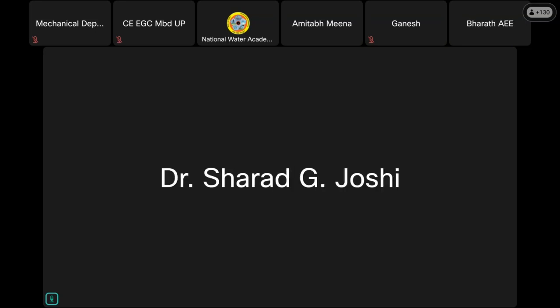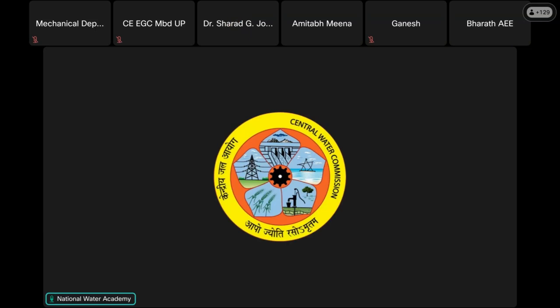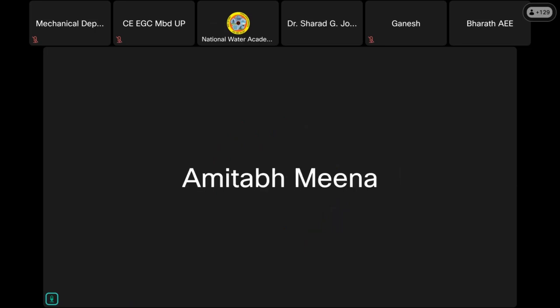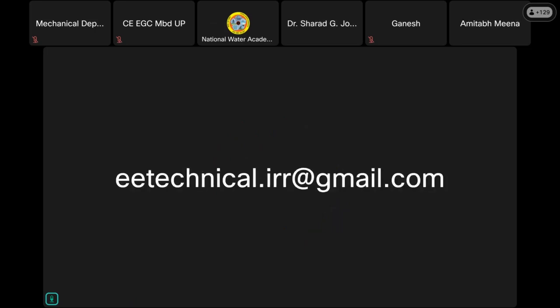Just search this IS code, sir, 11216. So please note that IS code, which the sir is mentioning, and you can find it. If it is not there, then you can ask through email to the NDSA. IS 11216 is the Code of Practice for Permeability Test for Masonry. In that, how much the permeability should be is given. Sir, can you please share for other dams also?